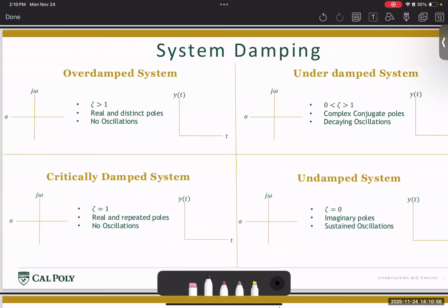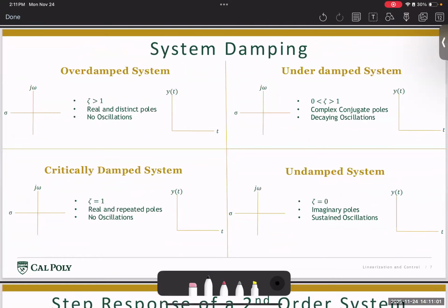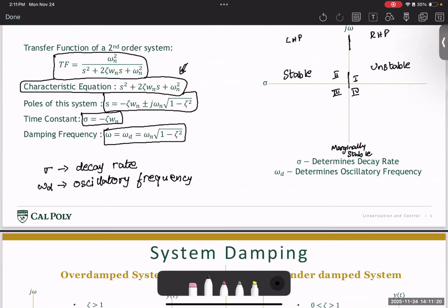Okay, awesome. Now, let's assume we have a typical second order system and we find the roots of the characteristic equation. So it basically tells us where the poles of the system lie. And let us assume that the poles are given by the solution for the characteristic equation, which in our case here, we said the solution for the system S is given as this equation, or substituting the definitions that we just had, then S is given by sigma plus or minus j omega d.